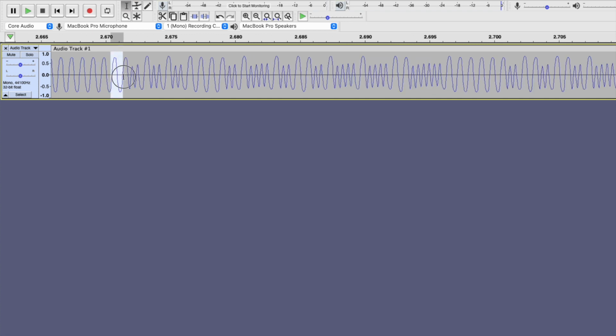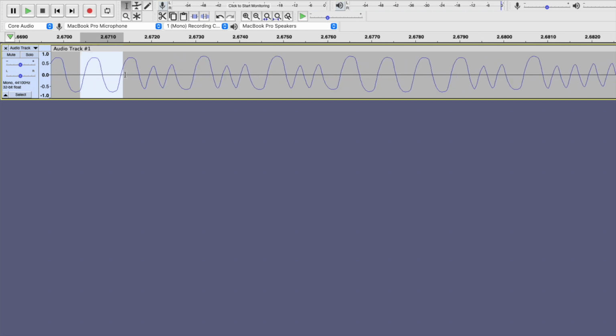You might have noticed the amplitude difference between the 2 frequencies due to the fact that the RC filter used is a low-pass filter. I could probably make that a bit more even without changing the board layout by swapping out a few capacitors and resistors.